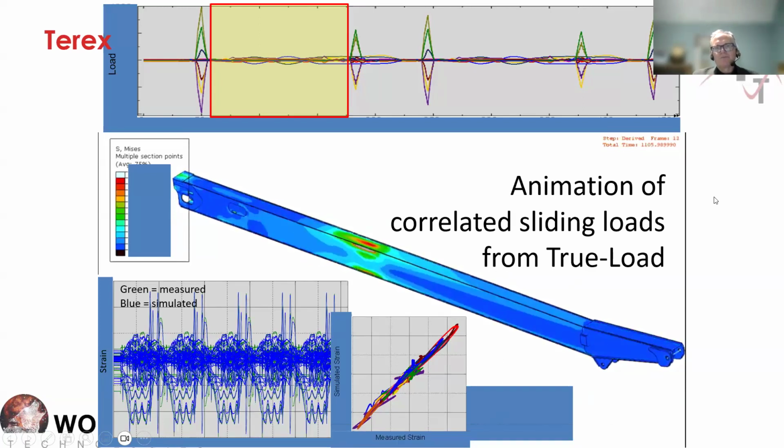So you look at this FEA response. This is a highly nonlinear FEA response, but everything going into the TrueLoad analysis is linear. When you think about doing a nonlinear analysis in FEA, as you go along your material curve nonlinearly, your analysis tool is doing a piecewise linear solution, and then it brings in the new material properties and does another piecewise linear solution.